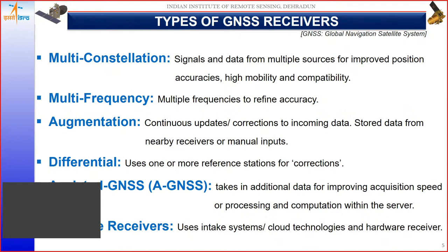For example, if you're looking at image referencing with very high resolution satellite data, better than 1 meter or maybe half a meter, though your smartphone has GPS, I mean GNSS, you cannot acquire the GCPs using the smartphone for such a purpose, which requires meter-level accuracy.